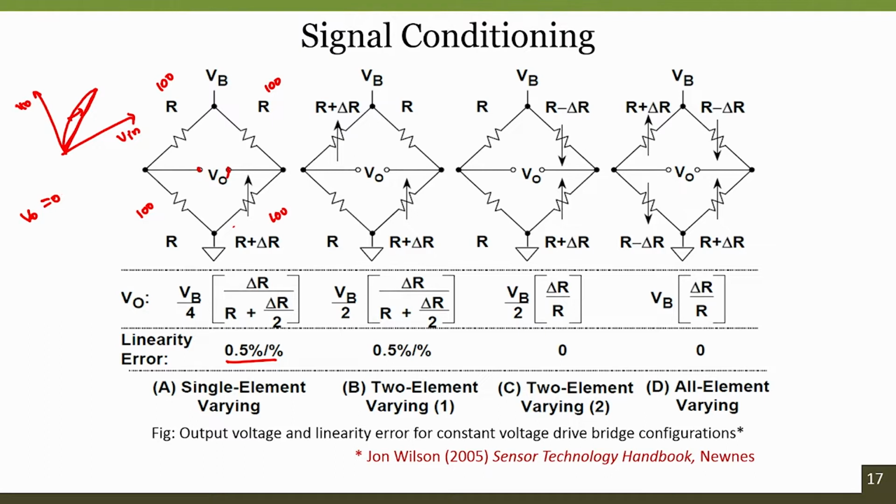So, when do you say there is no nonlinearity? In order to say the system does not have a nonlinearity, two different conditions have to be satisfied. One is superposition, the other one is scaling. If any one of these two does not satisfy, then the system is said to be nonlinear. So first consider the scaling factor. What is it? If y is equal to kx, and k is a constant throughout the operation of y or x, then the system satisfies the scaling factor. So the value of k should always be constant.